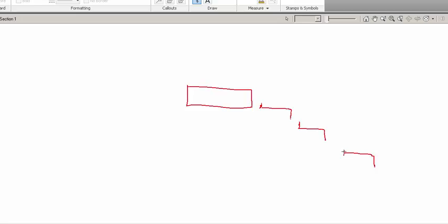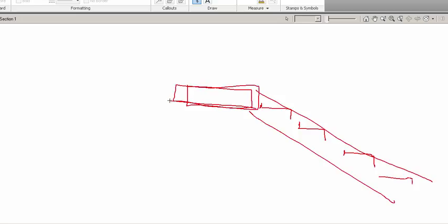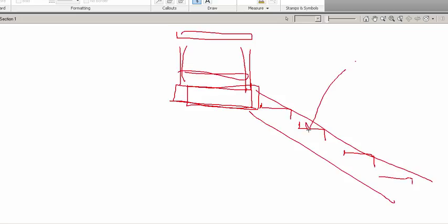And we'll create a set of stairs this way. We will weld these to a C-channel, running that way. Maybe use a C-channel right here, throw on some vertical rails, and we've got ourselves a steel staircase. So this would be plate. This would be some kind of plate size. The rest of it would be C-channel, and then some steel pipe, which we'll talk about in a second.